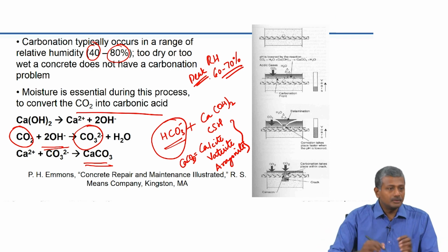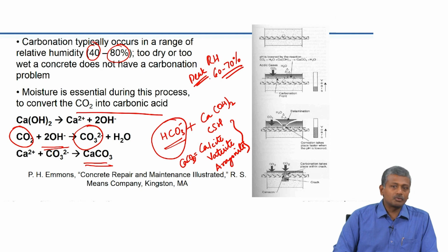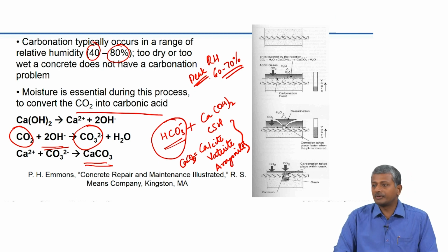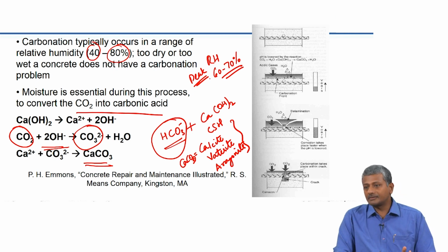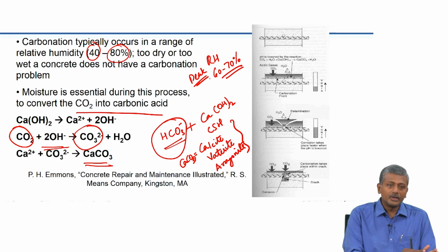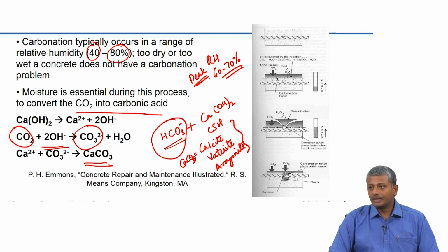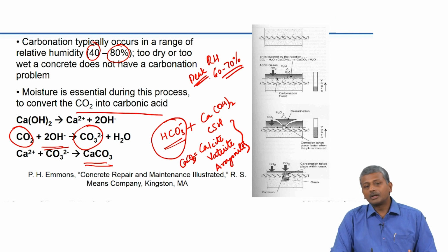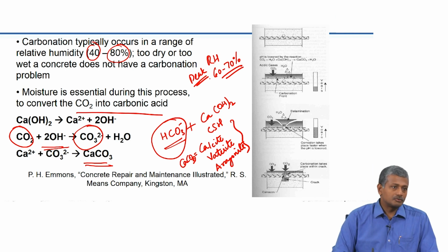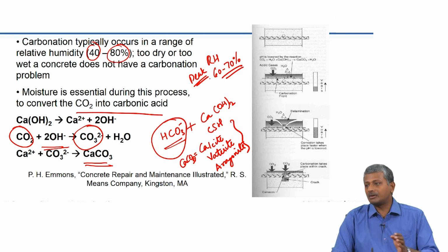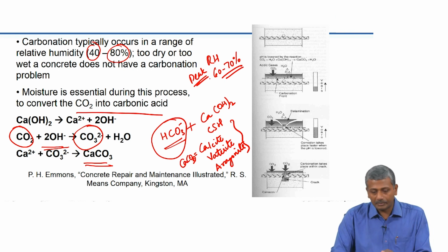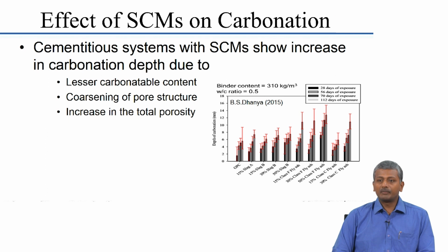But when you move inland, it is quite a reality that you can actually get this range of humidities almost on a constant basis, affecting your concrete structure. So, you have to be clear about the fact that when you are moving away from the coast, the dominant mechanism of damage of your concrete will change from chloride attack to carbonation, carbon dioxide attack. And both chloride and carbon dioxide are closely associated with the initiation of corrosion of the reinforcing steel. Okay, so, from both these perspectives, you need to address the issue of corrosion, which we will take up in the next chapter.